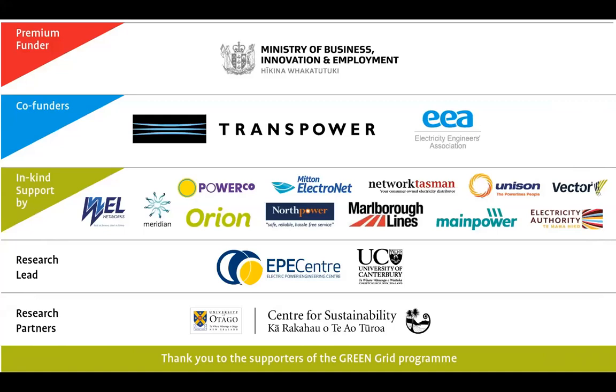Would vehicle to grid help offset the change in voltage from vehicles to photovoltaics? With electric vehicles, if you look at a typical scenario where people work away from home, often the electric vehicle's not at home when your PV's at its maximum generation. So yes, it will help, but it's probably not the silver bullet, because it will work for some households, people that work from home, or maybe they always leave an EV sitting in the garage and only use it occasionally. It helps to some degree, but it's not clear how much. We don't really have vehicle to grid at this stage. It's a very new thing, so it'll be interesting to see what happens there. But the timing's not quite right for the typical scenario for people that go out to work. Essentially it's just like a battery.